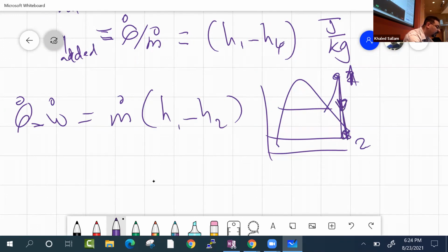may not be isentropic. It may be only adiabatic, but for sure the Q is 0 at the turbine, right? When you go to an actual power plant and put your hand on the thermal blanket they put under the turbine, you will feel some heat, and you will question: is it really adiabatic?